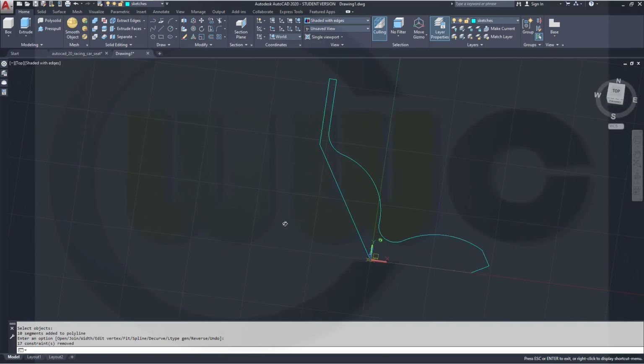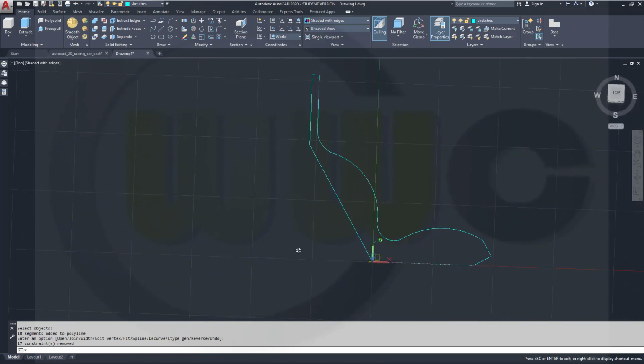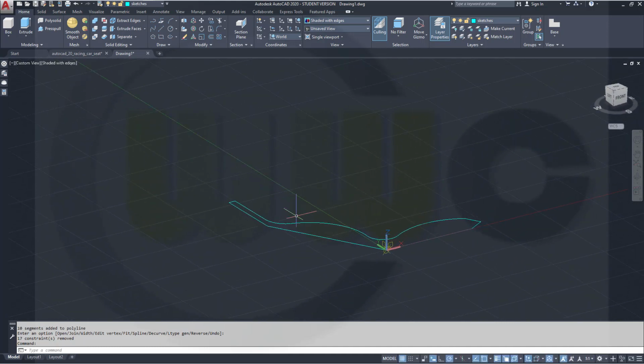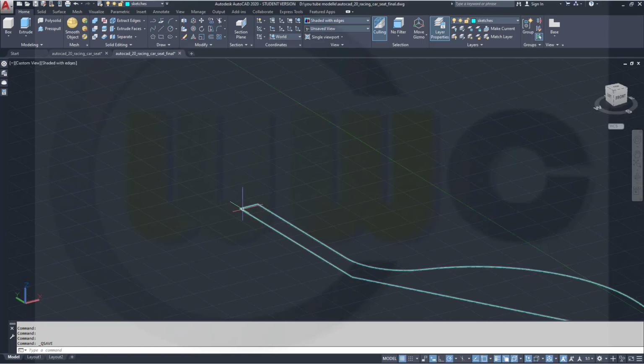Now there are no planes in AutoCAD, so I don't have to go for planes. I will need lines which go straight up from those points in that direction, in set direction. So these will be next. So let's go for another line. That line should start right here at this endpoint. And it should go straight up, and the length would be 100.